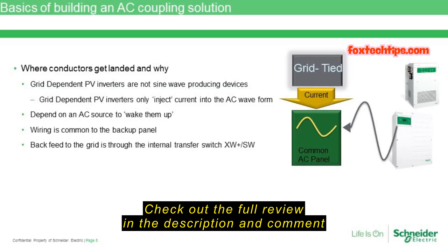So as the voltage on the battery starts to rise, what's going to happen is the XW Plus is actually going to start shifting its phase from, say, 60 hertz to 60.1, 60.2, up to 60.5 hertz. And at that point, we're outside the parameters for the grid tie inverter, and it's going to kick out, which is fine. It's not really going to hurt it. It's really made to do that, to stop producing power when the frequency gets beyond a certain range. But this guarantees that the investment that we've done in the batteries doesn't get harmed by accidentally overcharging them.